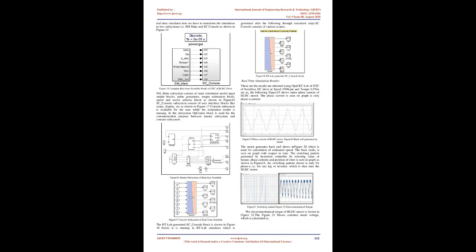OP4510 RT-LAB simulator, provided by Opal-RT Technologies. The host PC generates the real-time executable code, modifies the real-time parameters and records the data received from the simulator. The host PC and simulator are connected via an Ethernet LAN connection as shown in figure 14. Figure 14: RT-LAB simulator OP4510 with host computer, used to support the real-time realization of the complicated combined system.